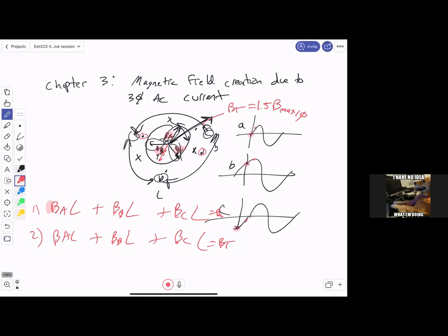The other question is, what is the speed of operation? That's based on the concept of how long this magnetic field needs to rotate along, if I'm looking at A, before I get back to a positive A. Well, we talked about a machine that has A and A prime here. What if I break that motor up in half? Now I erase this, and my motor is broken up in half. So I have another A here. So my A prime winding, we'll call this 1 and 1. This is how I basically divided the motor up in half. So I've got two A terms.